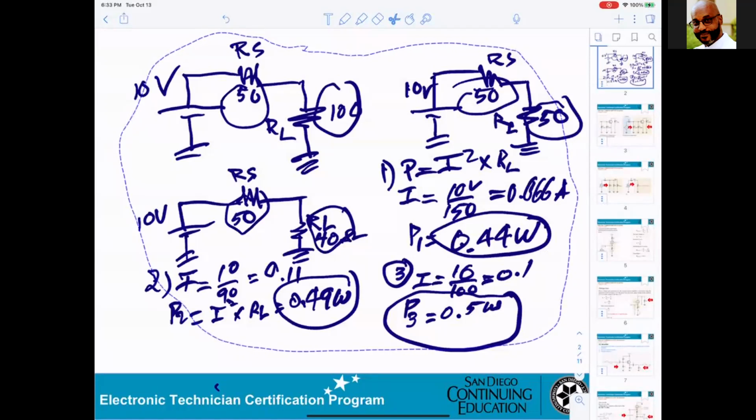It might help you to understand that. Let's say with the oscilloscope, you're using the signal generator to create your sine wave. The output from the signal generator would be RS, and when you touch onto the input of the circuit card, that would be your input to your amplifier. So that would be like the load. Yeah, in that sense, that would be the impedance that you would have to match.